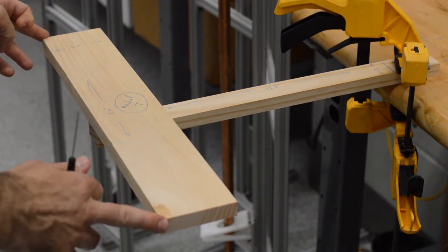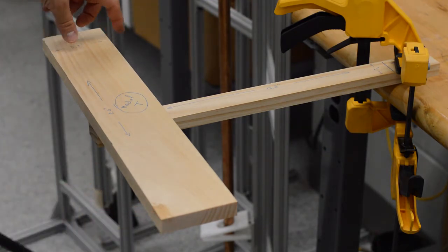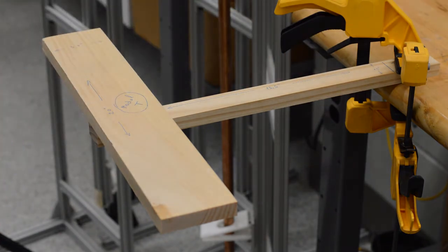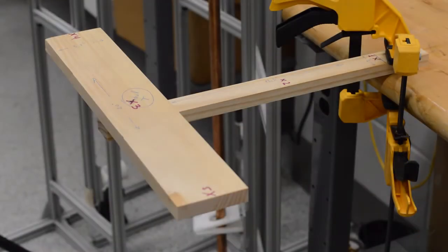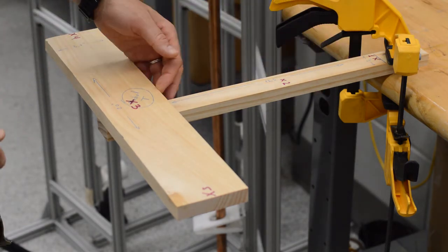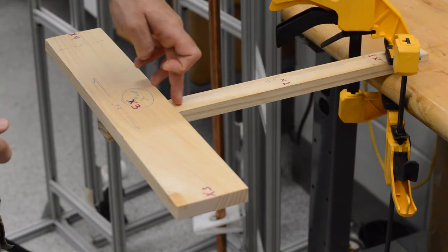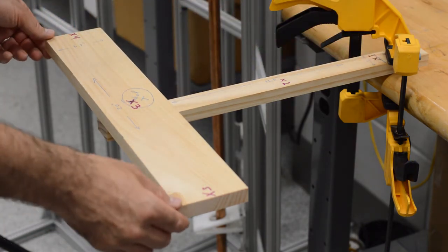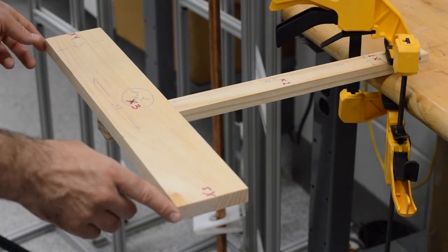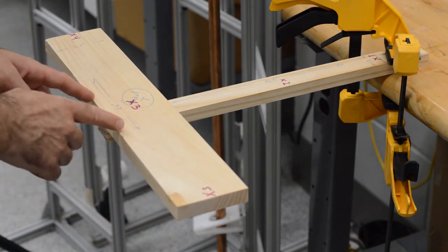It is 20 inches by 3.5 and 13.5 by 1.5. It is also clamped at the root to the table. In our tests, we are interested in the lower frequencies of this structure. So, for example, we want the first and the second bending of the vertical portion here, this torsion mode, and the bending of these two sections.